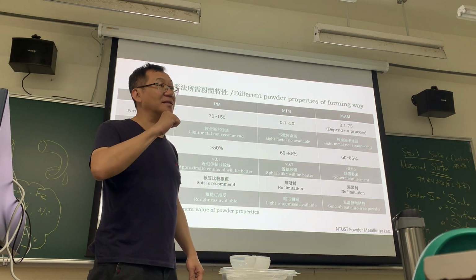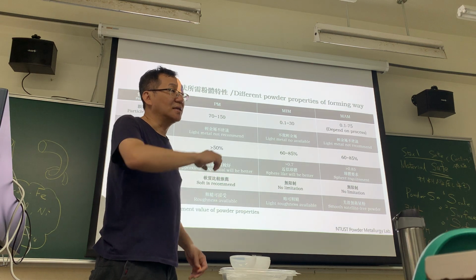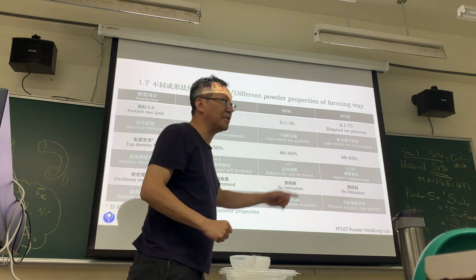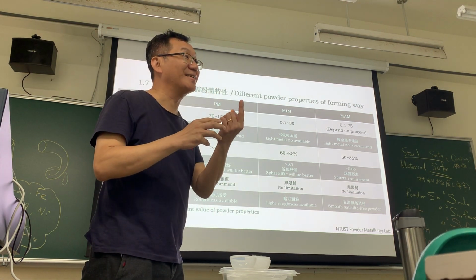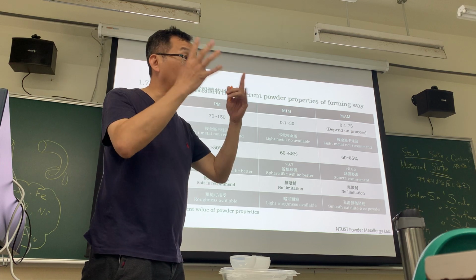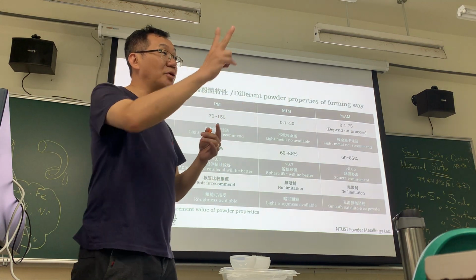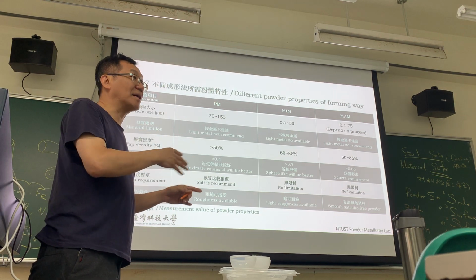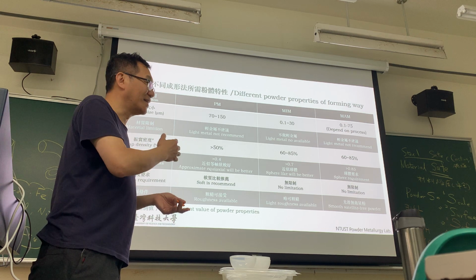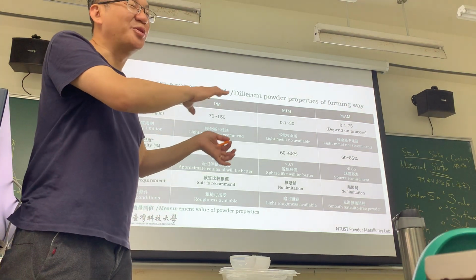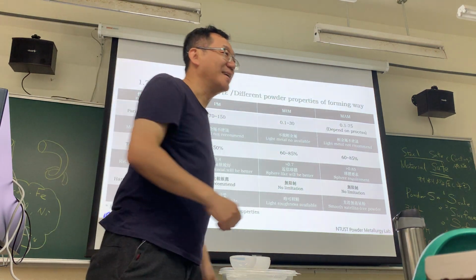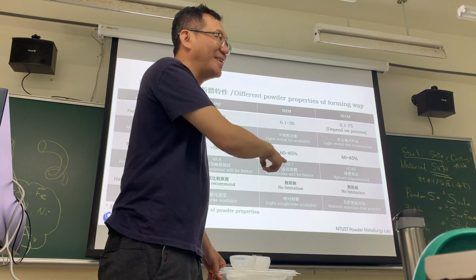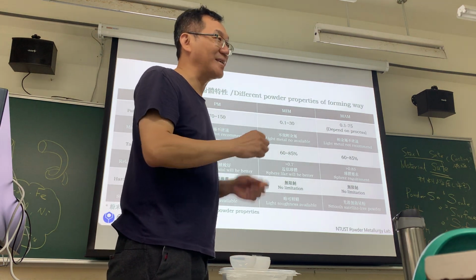So during the process, the temperature is higher. He just opened the filter and took it out. So the fine aluminum powder in the filter, then exploded. Okay, so the two operators lined up. Then this burning, then everybody was very hurt. They moved the machine to outside. Then they used water to pour on the machine. So it exploded a second time.